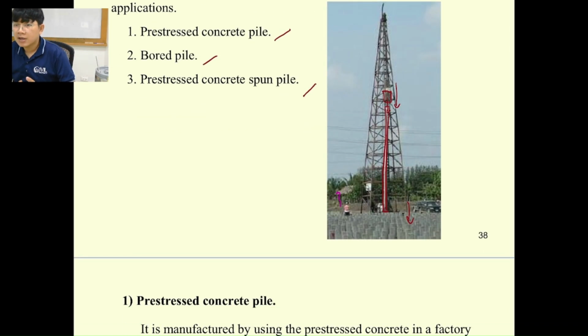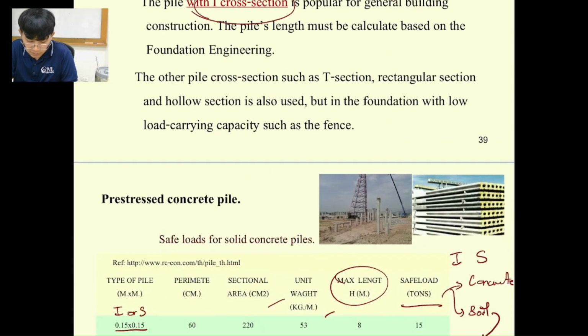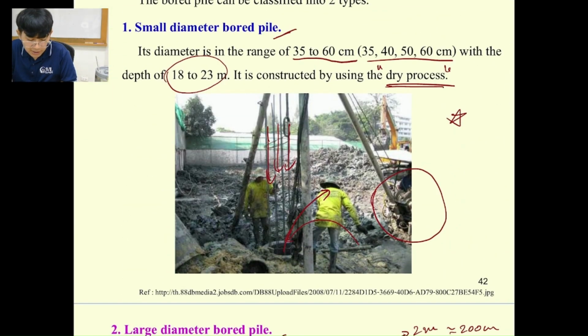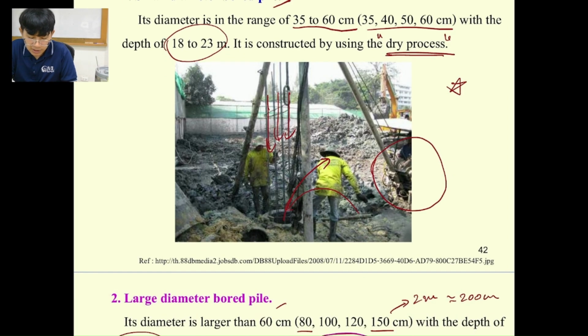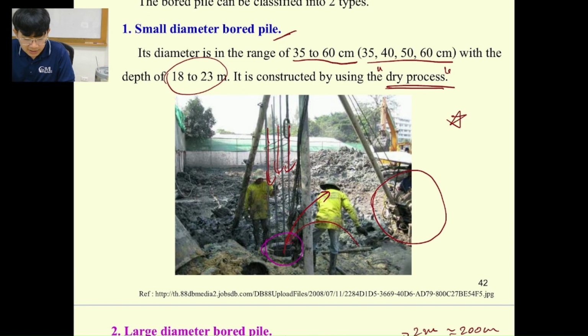Sometimes a house may experience some cracks from the vibration. So in Bangkok, when there are a lot of houses close to your property, they normally use bore pile instead of the driven pile, even though the driven pile is cheaper, because they have no choice.